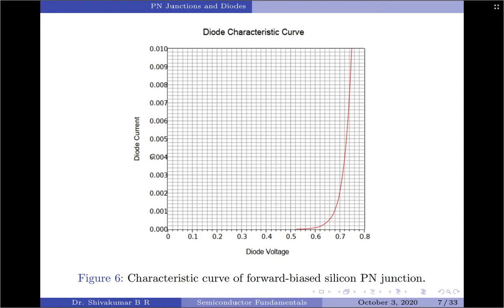While all silicon diodes will exhibit this same general shape, the precise value of current for a specific voltage will vary depending upon the device design. For potentials below 0.5 volts, the current is virtually non-existent. Above this, the current rises rapidly, becoming nearly vertical after approximately 0.7 volts. If the plot was recreated using a higher temperature, the effect would be to shift the curve towards the left, that is, a higher current for a given voltage.